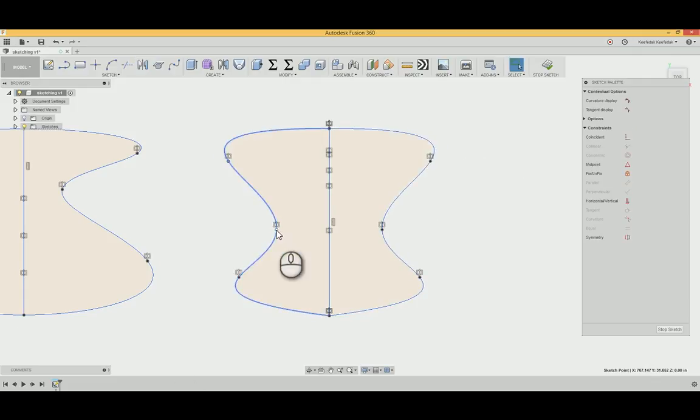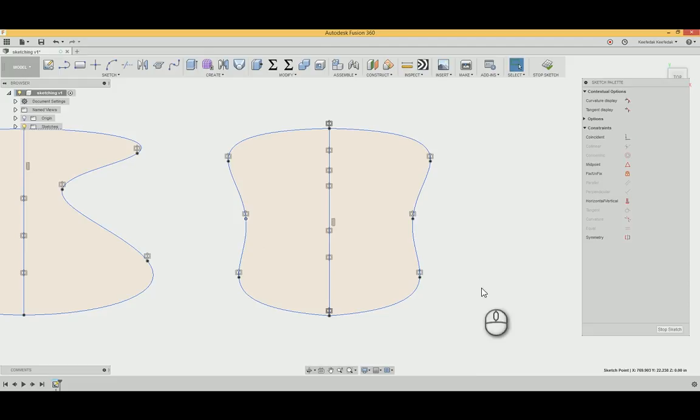So, quick question about the points. I missed something in the middle there. You're putting 2 points on either side of the line, and then you're making those symmetrical? I'm making them symmetrical to each other. Basically, they're symmetrical to the line in the middle. Okay, so the constraint is you click on one point and then the line.